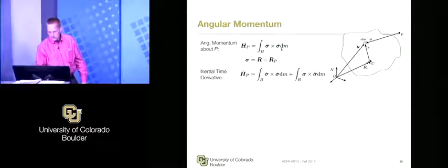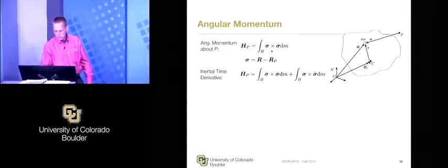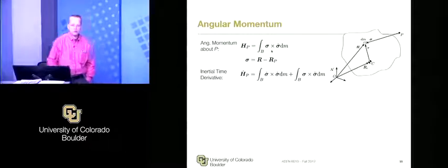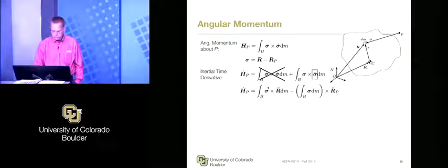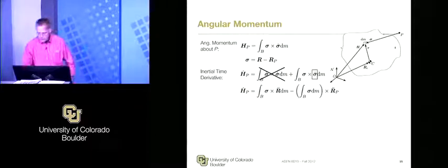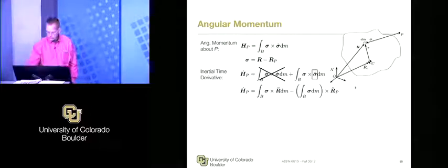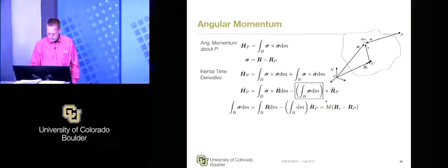And in this sense, linear momentum is mass times this velocity of sigma, the time rate of change of sigma that you have. So you write these things out, you get a vector crossed with itself, which would be 0. You get a sigma double dot. Well, sigma double dot is r double dot minus rp double dot, which we plug in. Rp right now is independent of this body integral, so it's outside. And so that gives you that term.